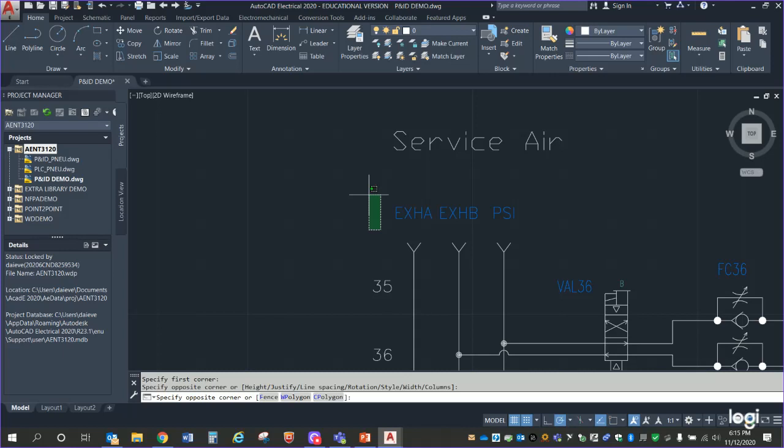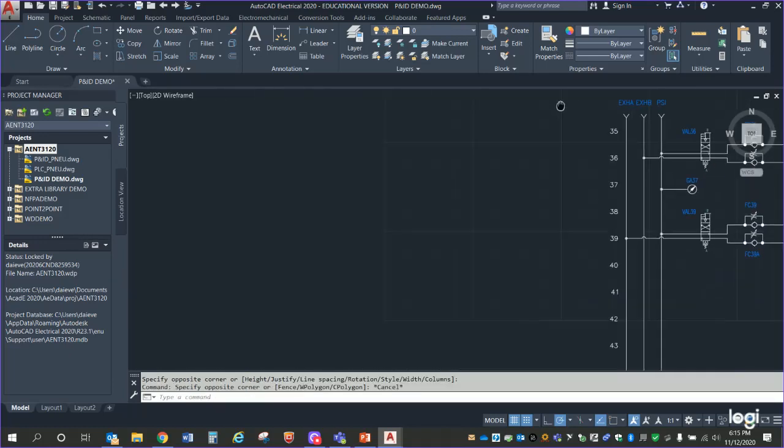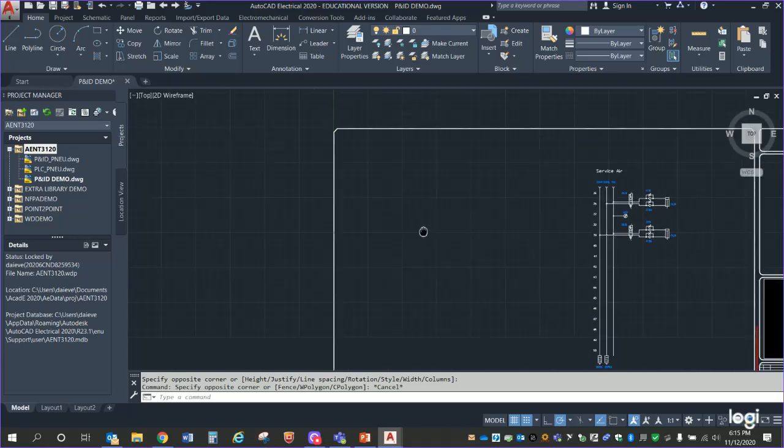Yes, because it's just like we put in fuses to protect transformers and motors and things like that. We put in these filters and these separators. We're trying to protect the cylinders. Cylinders are going to be very expensive. Well, for that matter, the solenoids too, right? Those control valves and the cylinders are the expensive components here, right? A nice little filter is pretty cheap considering what you're protecting.